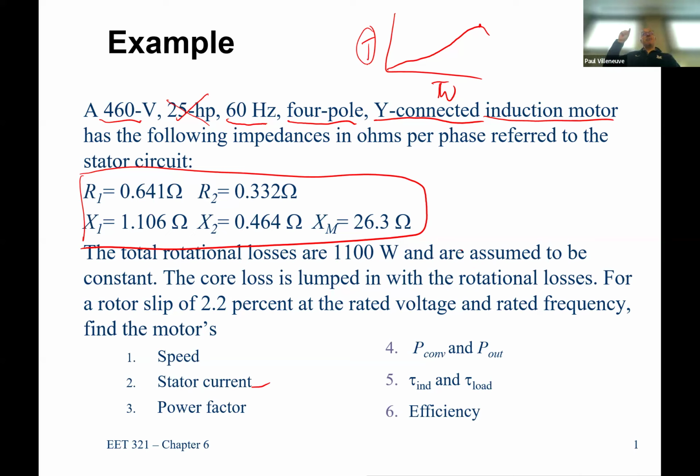Just a little thin piece of metal. You slide underneath the feet of stuff and you help line it up. And usually you have to be lined up within a millimeter or a thousandth of an inch. Really accurate. And so a lot of times mechanical engineers say, that's a lot of work to line things up, because you've got to pour a concrete slab. And then normally you put iron rails in it, because the concrete will move over time. The iron is usually pretty set, and it's a very flat surface. Okay, so you can use that as a support.